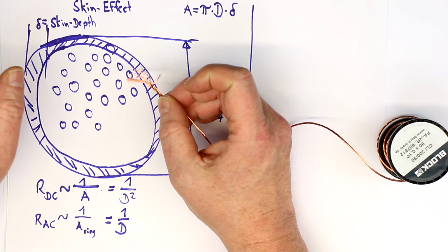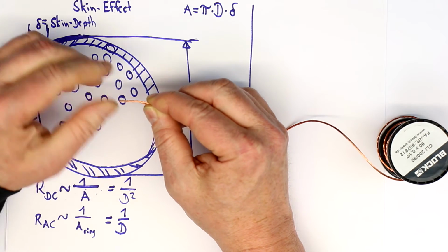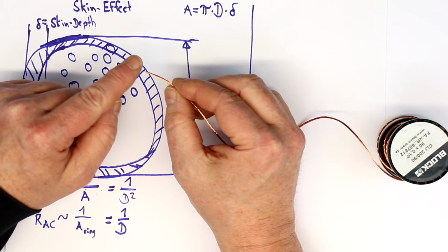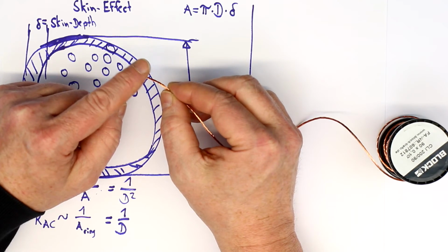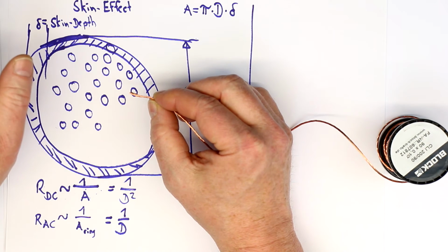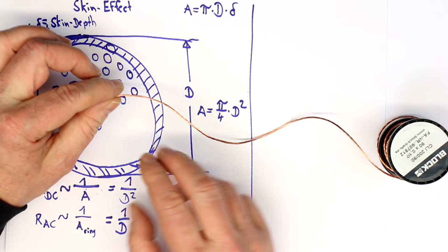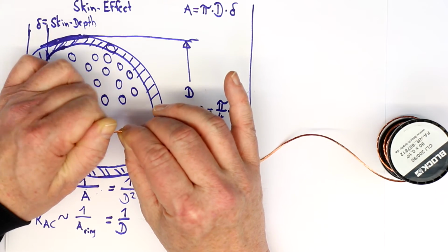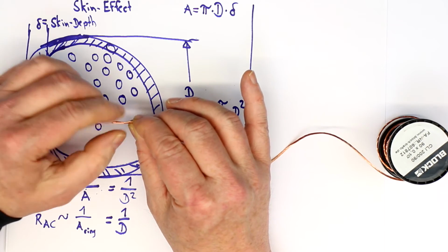And I've made a separate video on how to tin litz wire. You have to be quite careful in the end, just that every single litz wire must be tinned. If you leave out only one wire, you will get really bad effects, because a single non-tinned litz wire at the end will act like a winding which gives you a short.